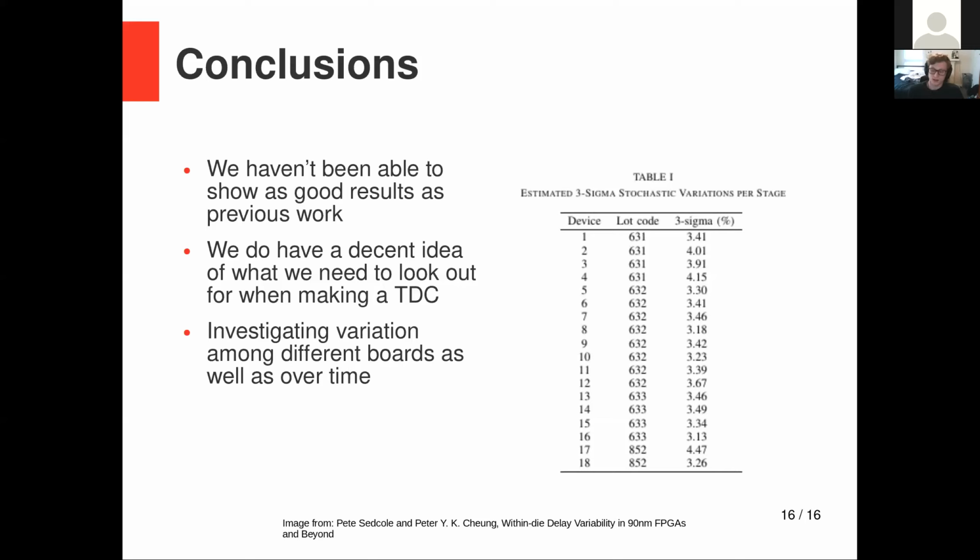And actually, it was just today that my professor proposed this: he thinks that after the first couple hundred hours of operation, we can actually see a significant difference in these delays. So it might be worthwhile for research groups wanting to do this to do sort of burn-in, like you might with speakers or headphones, and just run them nonstop to get rid of that variability. Because most of it happens early on in the lifetime, but also a good bit happens over time too. So characterizing that would also be important, because it may be that you need to recalibrate your board frequently. Otherwise, you're going to no longer have the results you think you have.